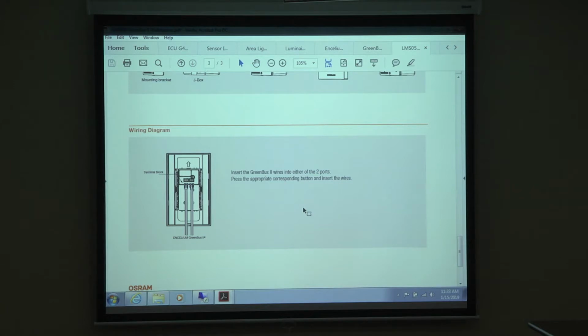how it's done from the factory, they give the installers an area, right? And they have devices in that area, and they say, okay, run the cable as you see fit. We had two methods. Let me give you a little bit of history. In the beginning, we had a method in which we did point-to-point controls, right? We would have a module here, there, and say, connect from this module to that module, to that module, to that module. And we hope that the installers would follow that train from here to here to here. So if a break happened in the channel, you would know directly. If it's a break here, you know exactly that the next device is this one right here.